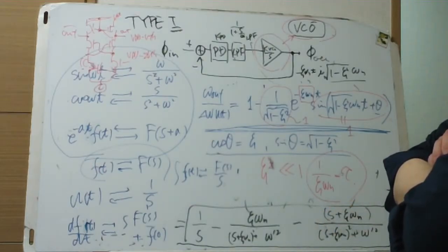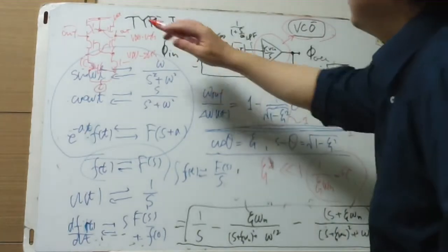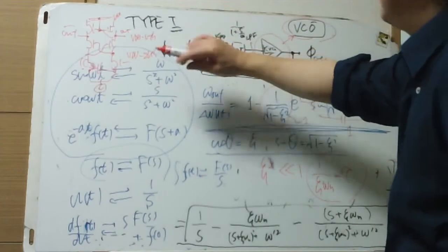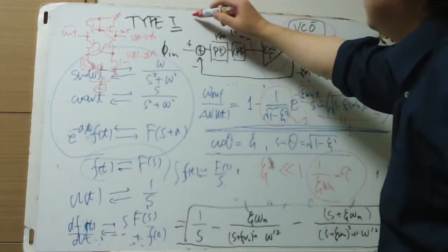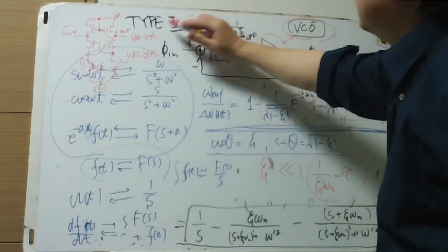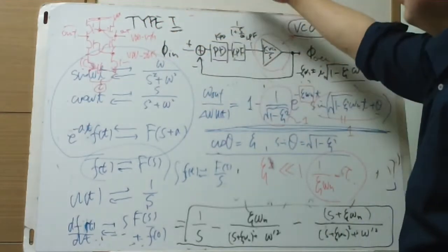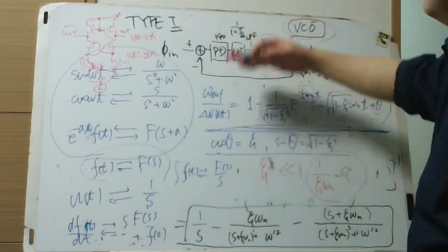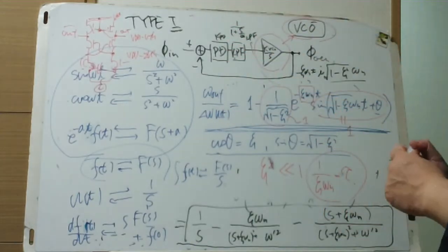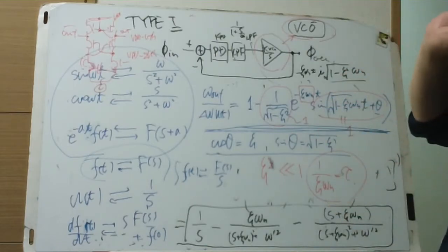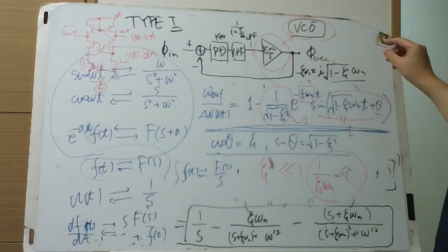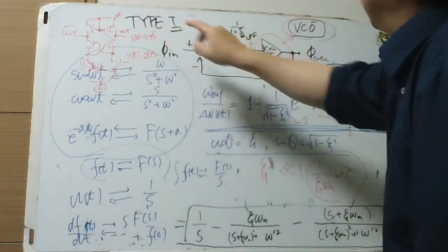And it oscillates. We need some buffer. Use maybe a self-biased inverter, a differential inverter, self-biased one, on the next stage, getting full range, rail to rail voltage, and an inverter also to shape the output and make the generated output.